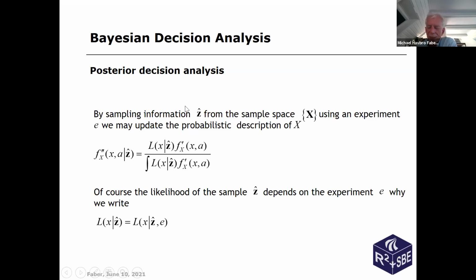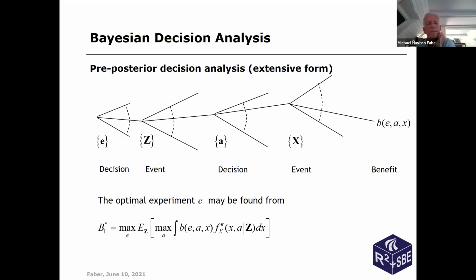And you see here that we need to model this likelihood. And traditionally, observations are considered to be independent in this Bayesian updating. So you make one inspection and get one observation one year, and then you get another one the next year, and you assume that they're independent, and then you use this information independently. But in reality, very often they are strongly dependent, and so you somehow overuse information. You use it twice, maybe sometimes. So we have to be very careful on that operation.